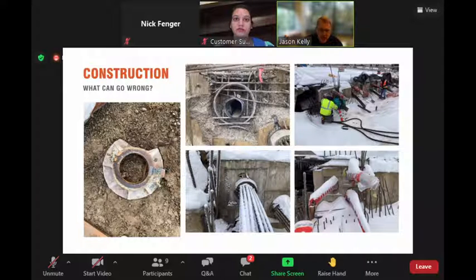The other criteria that we look to see if a bridge needs to be replaced is, is it functionally obsolete? And that might mean the bridge is in perfect condition, concrete's in great shape, the steel truss is fine, but it's got some functional problem. Maybe it's too narrow. Maybe it only has one lane and it needs 3 lanes because there's just too many cars that go across it, so it's a bottleneck. That's one thing we look for functionality. Maybe it's an old truss and trucks can't fit through it, or it's too narrow and trucks can't fit through it. That's a functional thing.